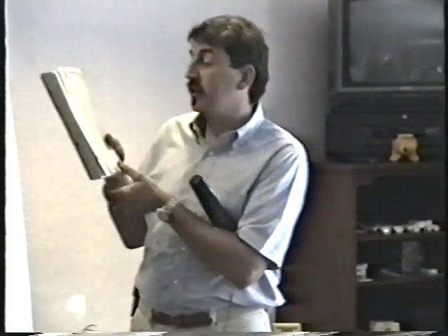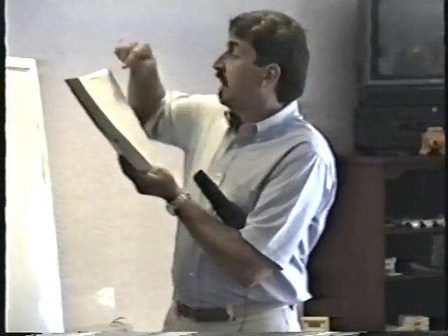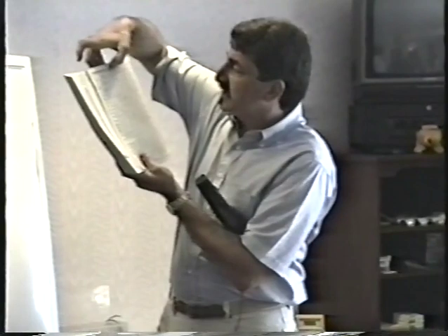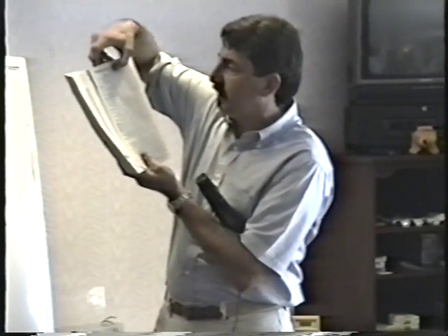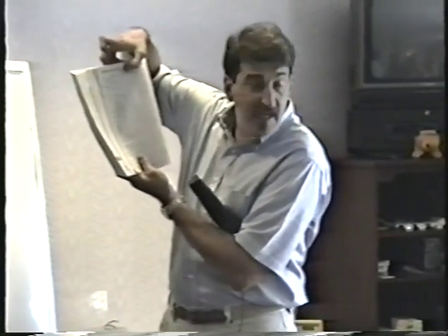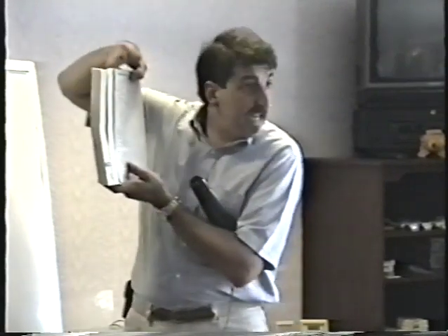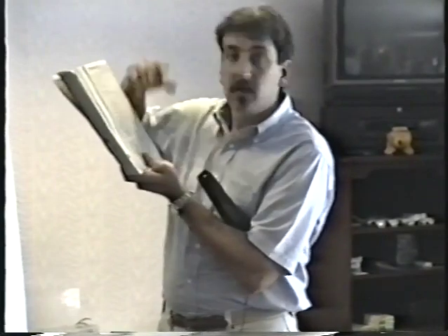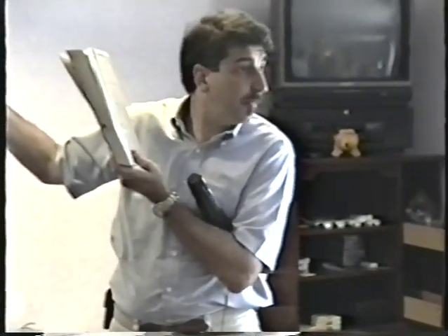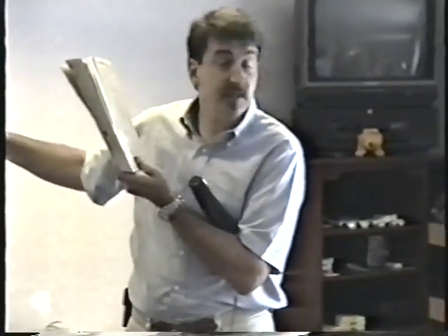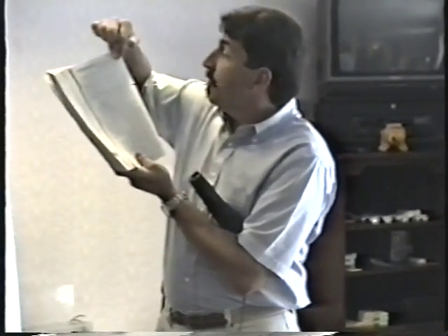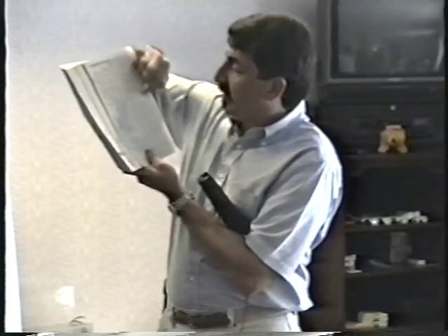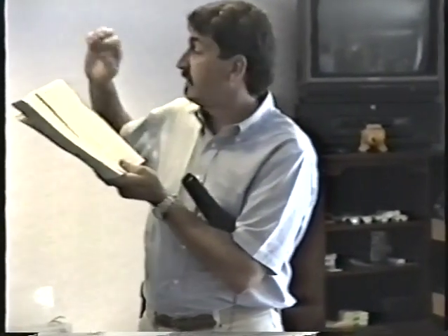Now, let's see what the specifications are. Remember, we've got some different voltage ratings, but the only one we're interested in is the second column over, collector to emitter volts. Remember that? V sub CEO, or as it says here, BV, breakdown voltage. What does it say about the voltage? 60. We know that's true. We just looked that up. 60 volts. So that's cool. Maximum collector current, I sub C, 15. That's true. That was the original specs.